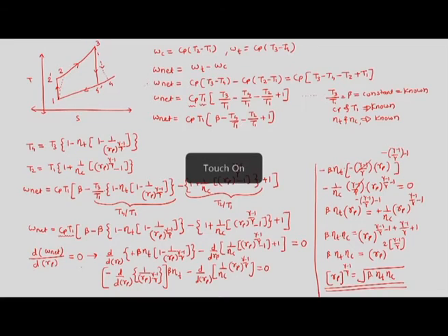So, this is how the part for non-ideal components is. Now, we will see some examples. We will see how to solve an example and what things are generally given in an example. The example says that there is a gas turbine which operates on a pressure ratio of 6. The inlet air temperature to the compressor is 300 Kelvin and the air enters the turbine at 577 degrees Celsius. If the volume flow rate of air is 240 meter cube per second, then calculate the power output in megawatt for the gas turbine power plant. So, what is given to us?